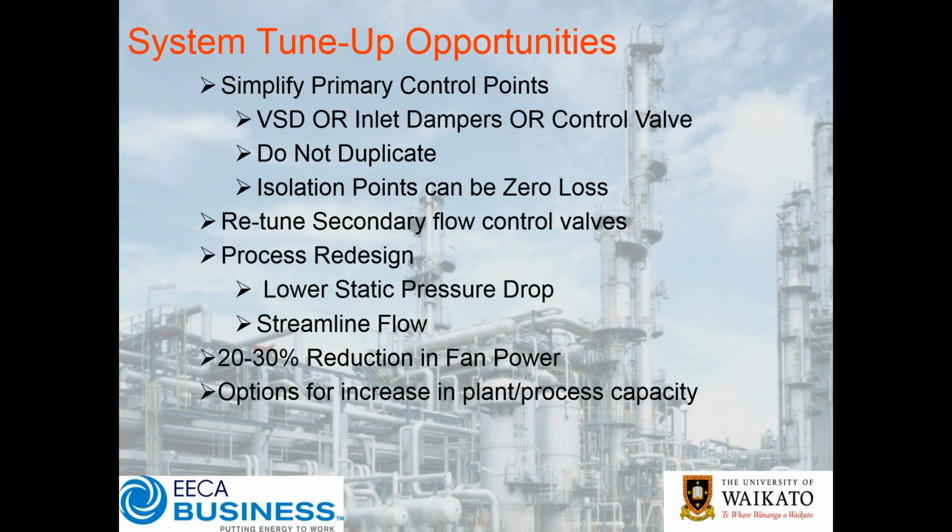Remembering that if you do need these isolation points, they can be zero loss. They can be engineered so that they don't actually have anything in the way of the airflow when you're running, as opposed to having big butterfly valves that very easily might not be fully open, and if they are open they could actually cause problems. And we've got some examples I'll show you in just a minute where even though you think it's okay, my butterfly's open at 100%, therefore it's not disturbing the flow, it may well be, and we'll show you an example of that in just a minute.